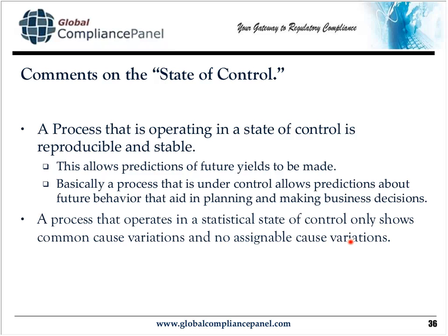Now, the whole idea behind process validation and all this work you're doing is to eliminate assignable cause variation. And then, if necessary, if the common cause variation is too large, for instance, if common cause is so large that it gives you, say, 5% of a lot always fails, then it tells you you need to go into your process and work on the process to reduce these failures.